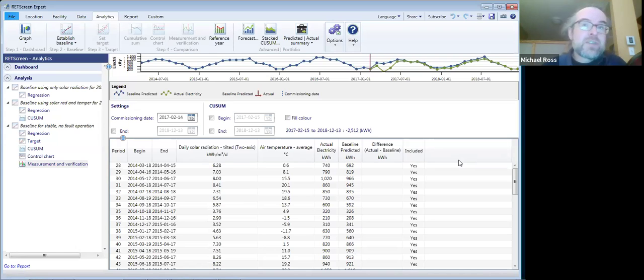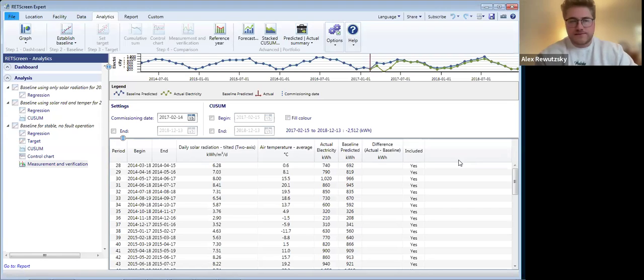The only concern I have there is make sure you do understand what the numbers are. Don't blindly accept every number in there. Ensure that whatever RETScreen proposes is valid for your particular situation. But if you appreciate speed over having complete control, then the virtual energy analyzer is an obvious choice. If, like me, you're detail oriented and you want to make sure that you understand every last detail of your analysis, then a blank analysis is not a bad way to go. Beautiful.